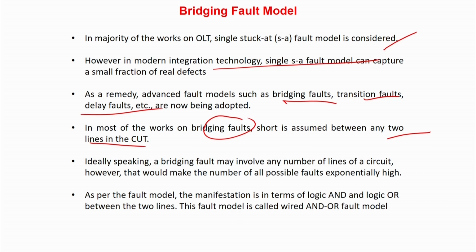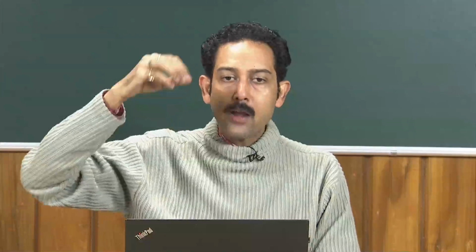If I reduce the test pattern generation time by finding a good alternative path for propagation etc., it does not hamper your quality of service. But if I reduce the number of test patterns, there can be multiple ways of doing it. One can be by slightly reducing the fault coverage. You can say that this part of the circuit is not prone to failure, so I do not need to test it.